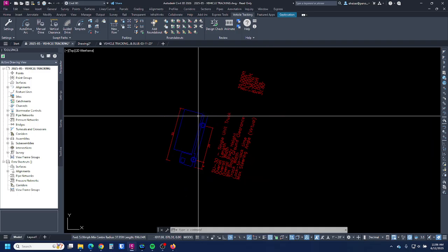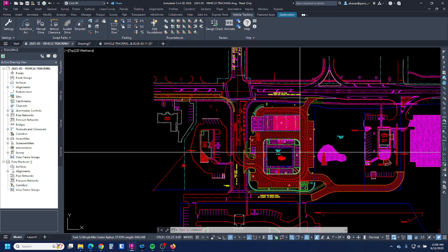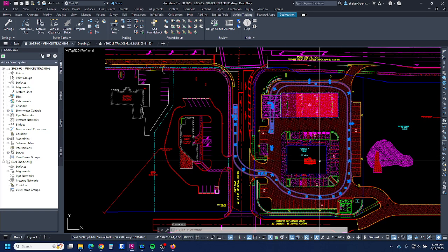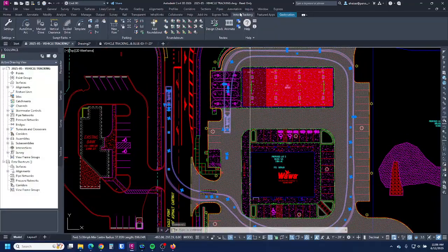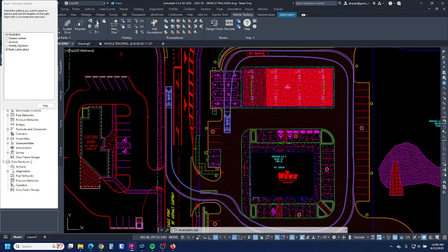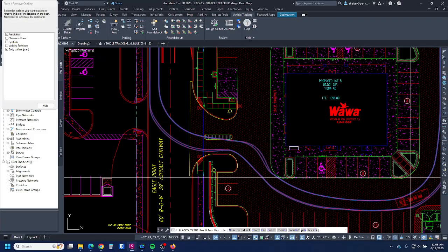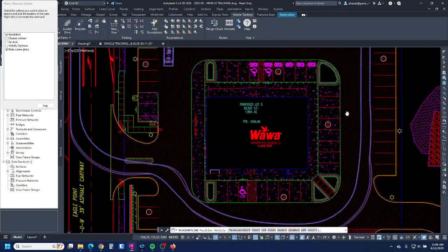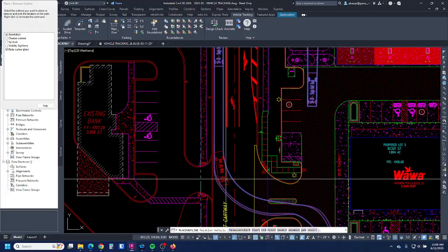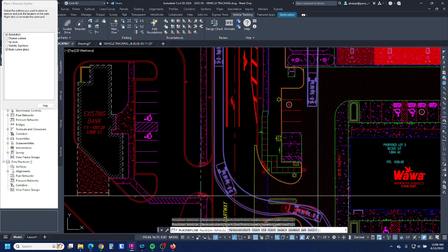The other thing I want to show you how to do is add a vehicle outline to a path. Again, you have to have a movement in the drawing. You select it, then you go to your vehicle tracking tab in the ribbon, and you are looking for the Place Outline button. It's a square with 2 dashed arcs, one on either side of it. So we're going to click it. Then you can just mouse along the path where you want to click them. It's actually kind of neat to use, even if you don't add it, as a way to visualize what a vehicle might be doing on your turning movement. But if you want to place one, which I often do on turns, you just click wherever you want it to be.